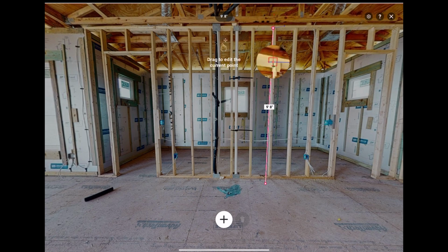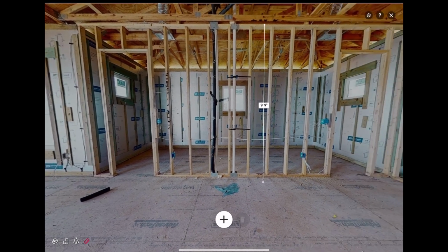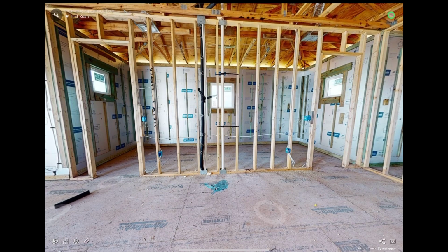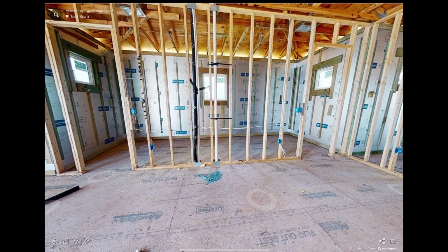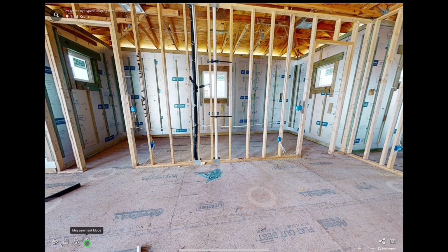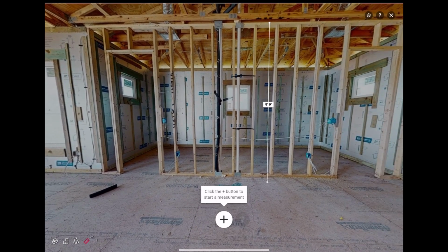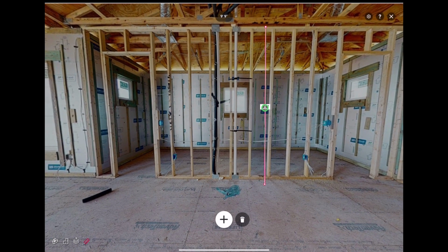And let's say I want to get an idea of what the ceiling height is here. I can move that right to where I want. And now I have my measurement. I can click the green check mark if I'm done, and that measurement will stay there in the scan when I'm in measure mode. If I click the X in the top right corner here, I'm out of measure mode and that little dimension goes away. But if I click measure mode again, there is my dimension, and it has popped up again. If I want to get rid of that dimension, I can just click and highlight it and click trash.